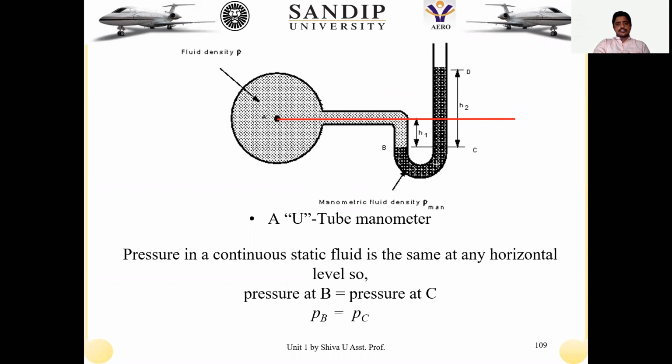At the point B, you can see there are two types of liquids available. That means by using the U-tube manometer, we can even measure the pressure by using two liquids. It is upon the user's requirement whether we go for two liquids or one liquid. The zones are shown in two shaded colors, one gray and another dark black. This shaded region we will call the manometric fluid.